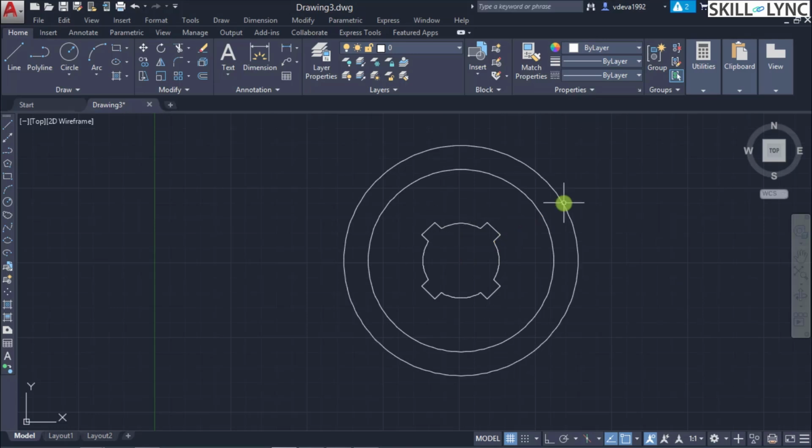154 mm. So now the slot, as you could see, from the center point along this axis, it is 15 degrees towards this and this side. We can use the same option that we have done earlier, but now let us use the line command.